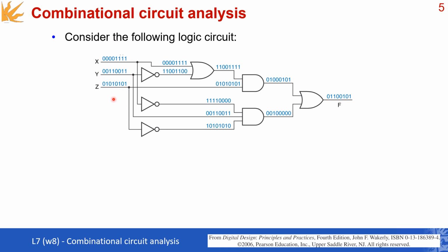Now, as a small trick, in order to make this process safely and very fast, you can start with the first variable, where half of them are zeros and the other half are ones. We need 8 different values here because you got 3 input variables, so this means 2 to the power of 3. So the first 4 are zeros and the other 4 are ones. When you go to the next variable, the remaining combinations are for 2 variables, so this actually gives you 2 to the power of 2 combinations.